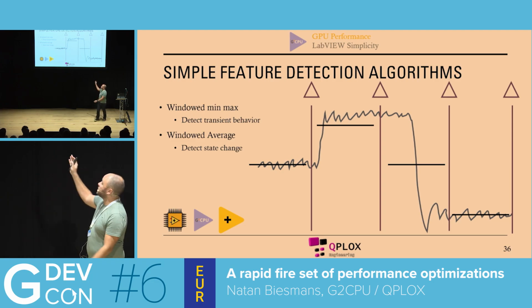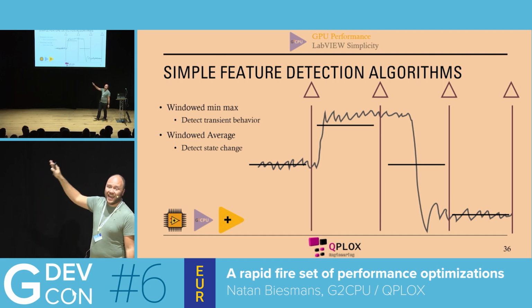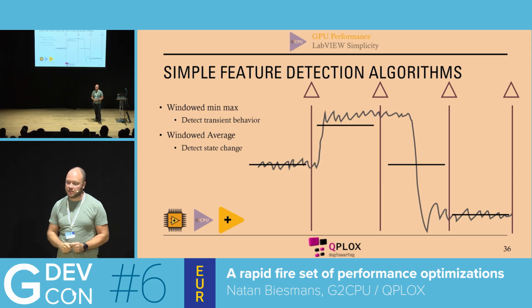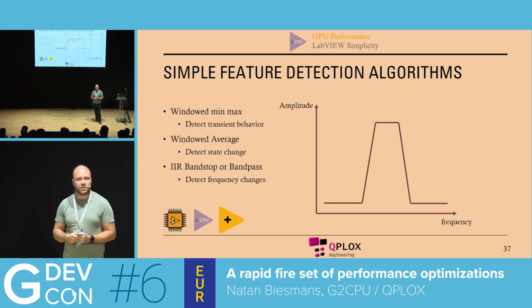Again, something like this is extremely cheap to implement on the FPGA, GPU, and CPU. For example, on the FPGA, it's just adding the values until you're at the end of the window and doing your bit shifts. Couldn't make it much cheaper than that. Simple addition, that's all that's happening, with a little counter to see when you're at the end of the window.